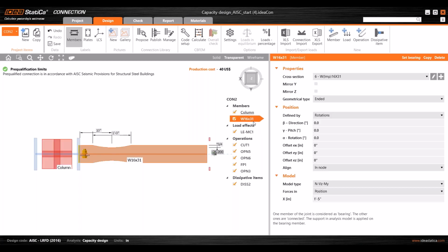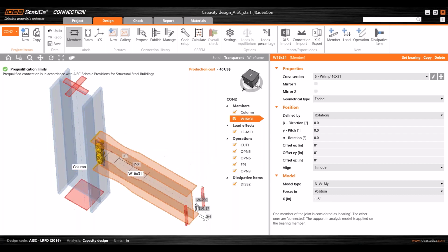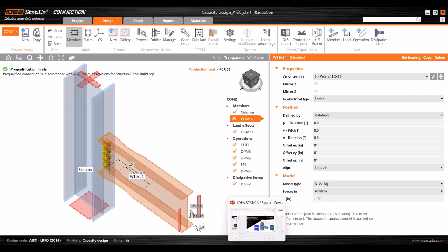And then you select the beam, okay? And you input that position. So that position is 17 inches, 1 foot 5 inches over here, all right? Again, we are inputting the maximum probable moment over here in this position and the shear force as well in that position, okay? Then the next step, let me go back to the presentation here.